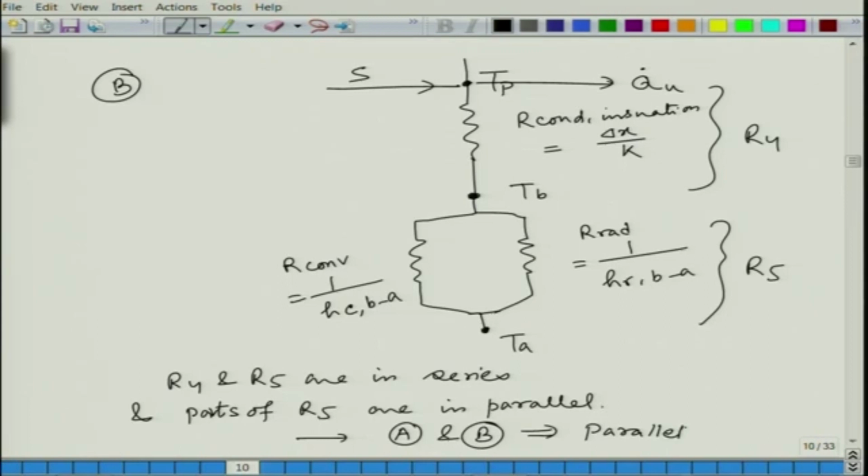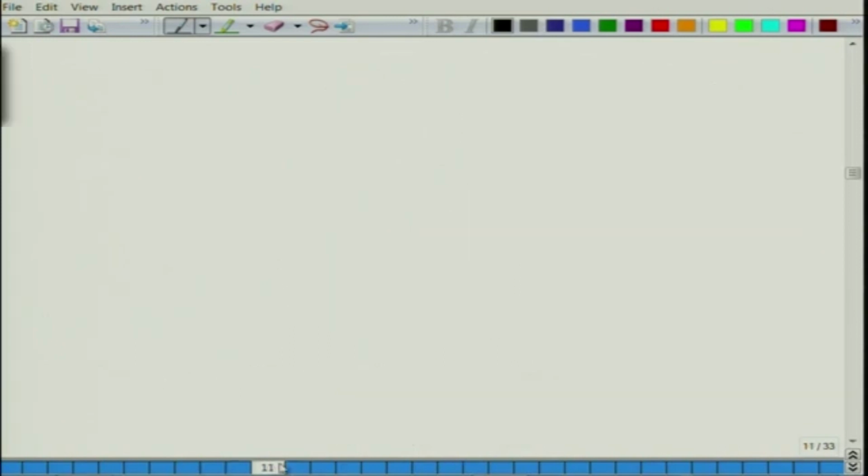So, this is the overall heat loss thermal circuit that we are given here. Now, if we wish to look at the individual resistances, then we can write Q loss top, that is the rate of heat loss through the top, to be h_c,p-c1 (T_p minus T_c1).